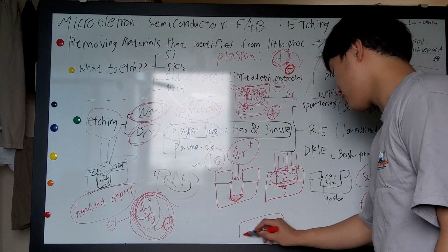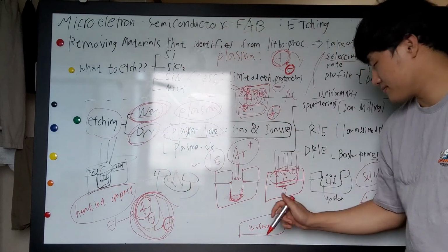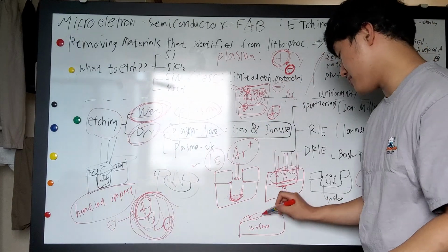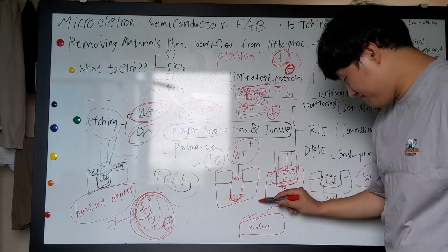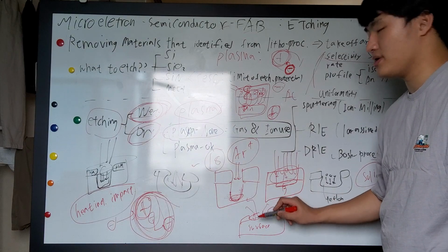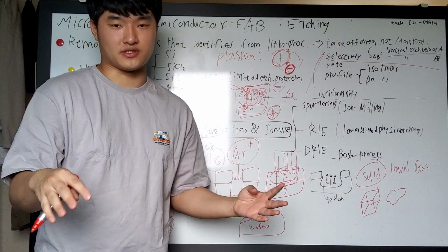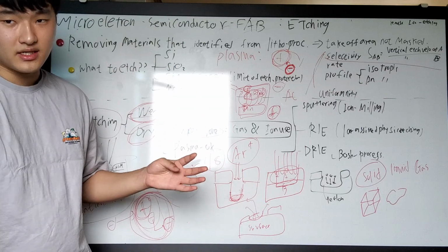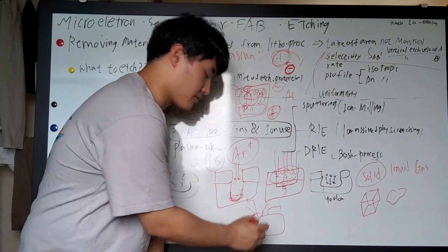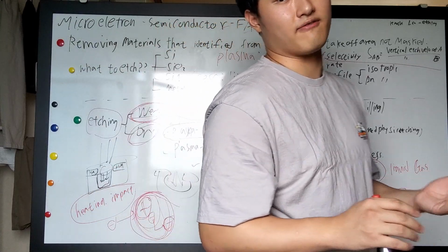If there is a surface that we want to make, and we keep hitting the metal surface by the ion impact, sorry, plasma, then the debris that came up from the surface will remain in the process, and as time passes, the debris will be deposited as a layer, and this will make somewhat unwanted effects or results.